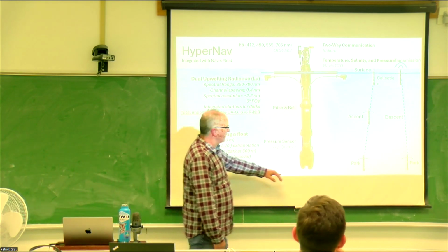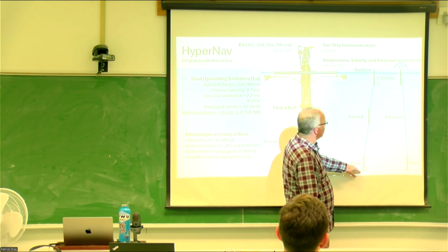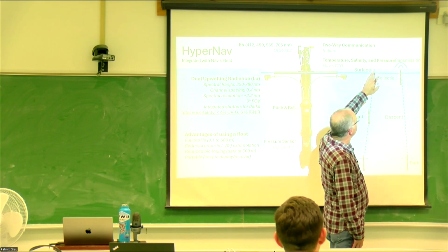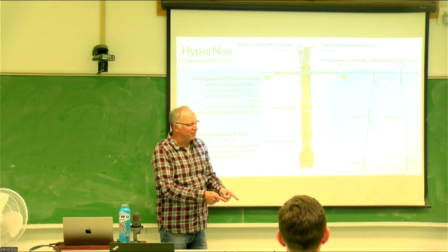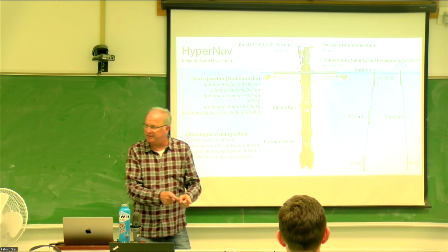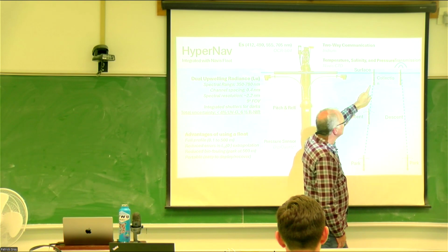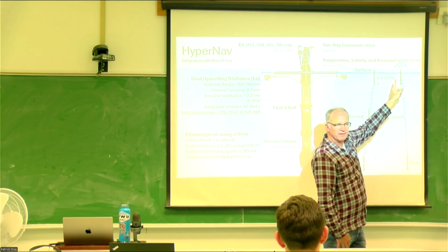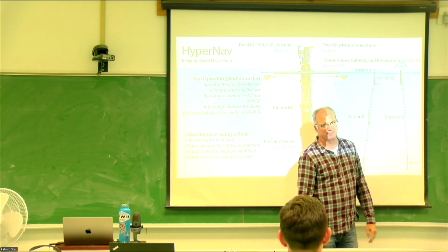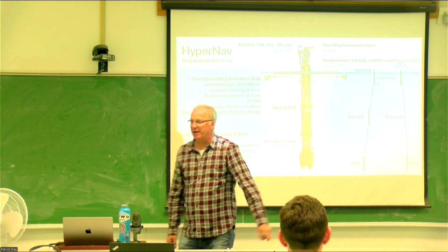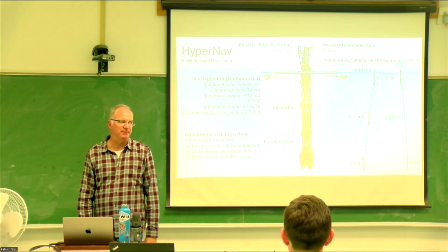So park at a depth, park overnight, time my ascent rate such that it pops out and starts connecting. Right as the satellite's going over, I make a 3 to 5 minute measurement, collect data there. I spend an hour and a half sitting at the surface trying to pump that data through Iridium. So that's my number one power consumption, Iridium.